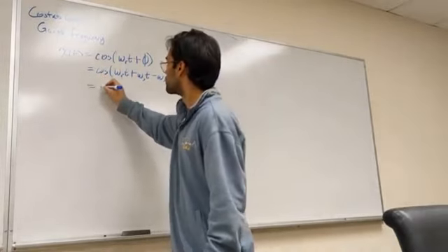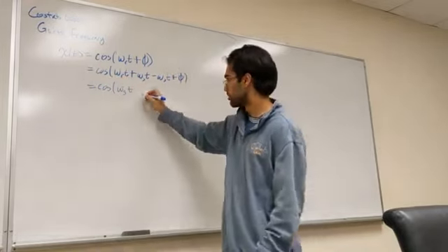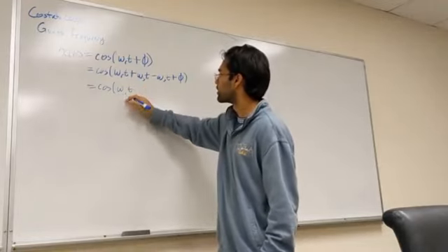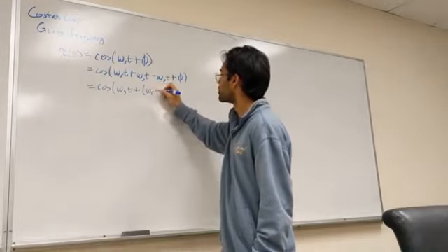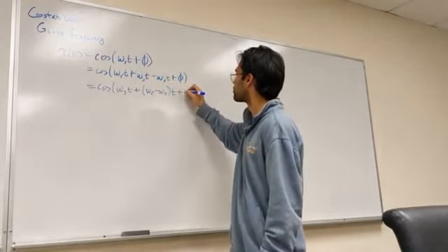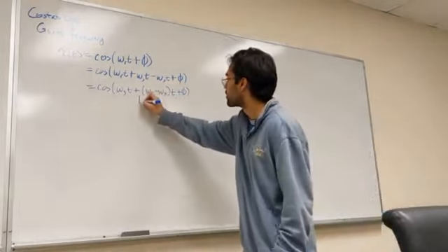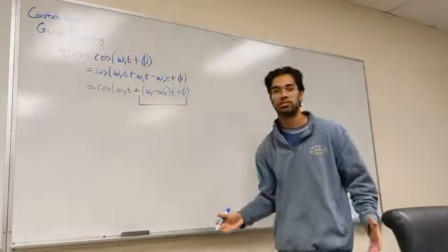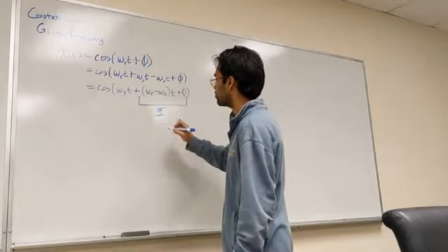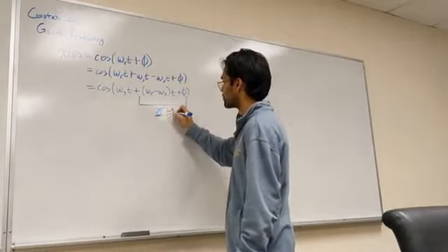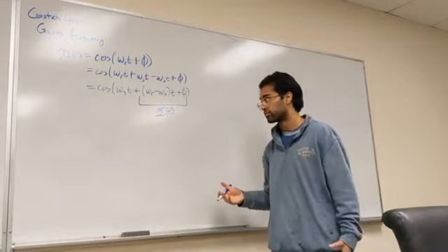Then we're going to put this in terms of our transmitted frequency: omega s, sent frequency, plus (omega r minus omega s) t plus phase. The point of this manipulation is that we can take this whole component, this offset that we don't know, and lump it into some phase function, some arbitrary function. This is a function we're going to try and keep track of.